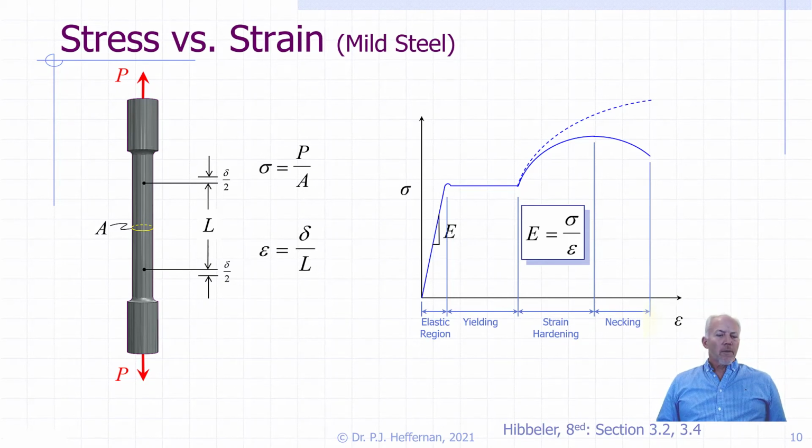So a quick note on what we actually physically measure in the lab. How did we get the load? Is there some instrument that actually measures load? The reality is what we have is a calibrated piece of the instrument called a load cell, where we know the relationship between load and displacement. And what is actually being measured is the displacement. And then through that calibration, we are able to interpret that as load.